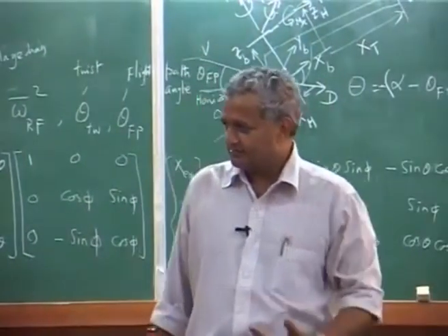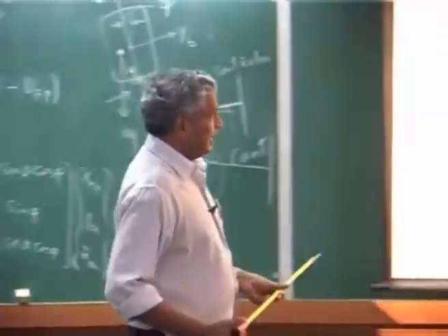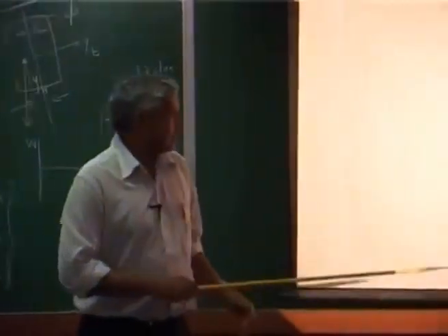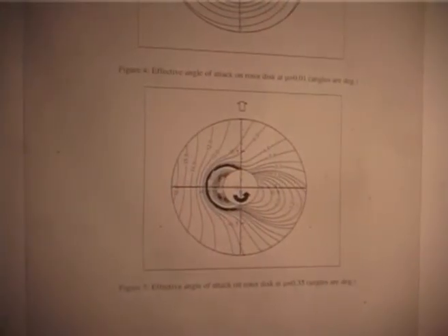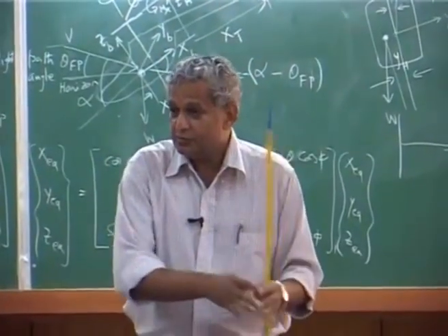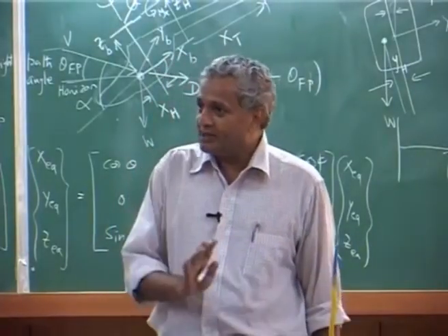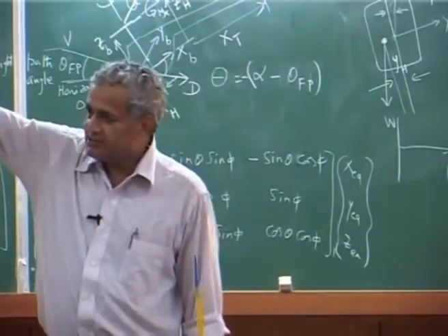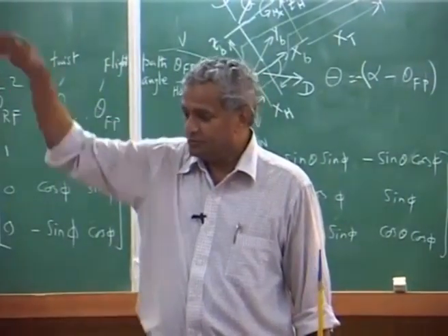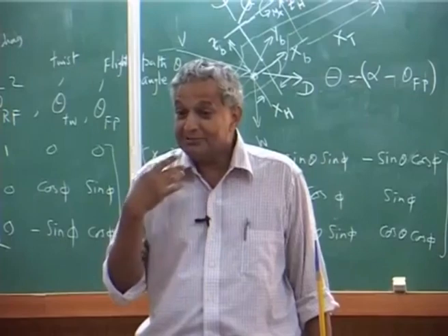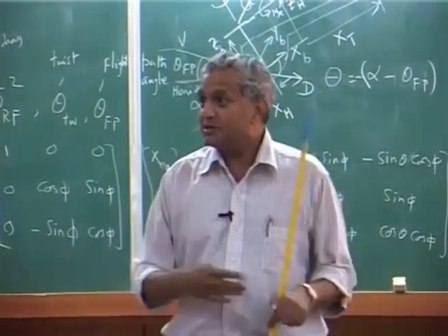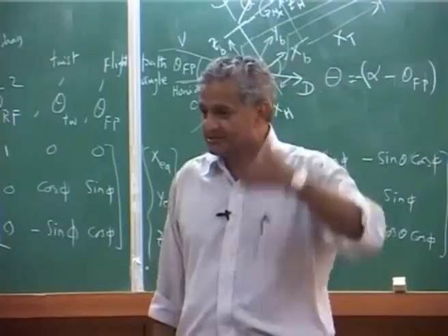So, we took the data from a textbook. That is why at high speed you start stalling on the other side, and that will give you vibratory loads, which we computed. This is just for you to know how you do the trim problem, but the trim problem will give you the vibration load as a part of the solution. That is why you do not solve trim separately and aeroelastic load separately. You have to get both of them simultaneously. But simultaneously means that in one shot you will not be able to solve it, you need iteration.